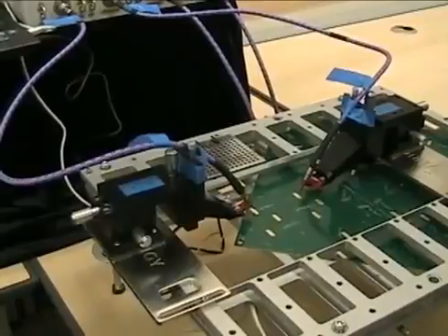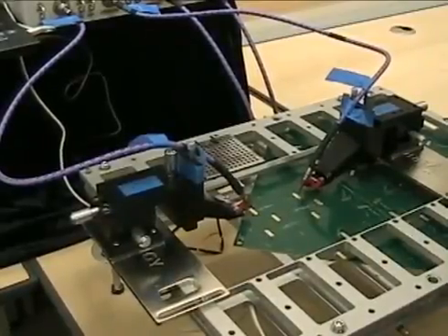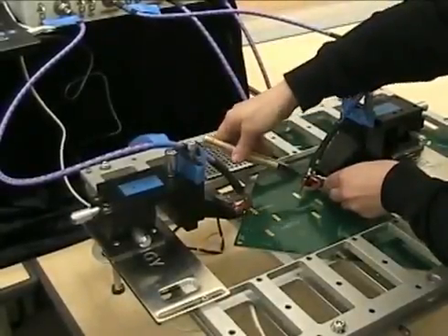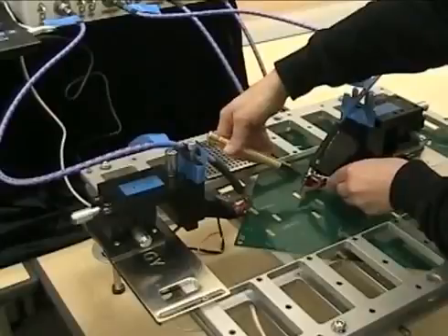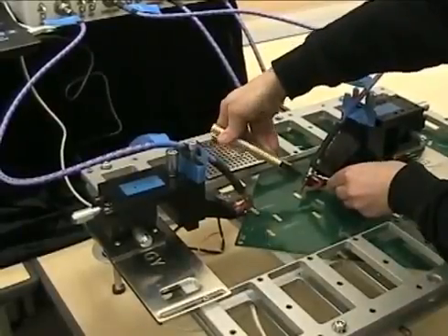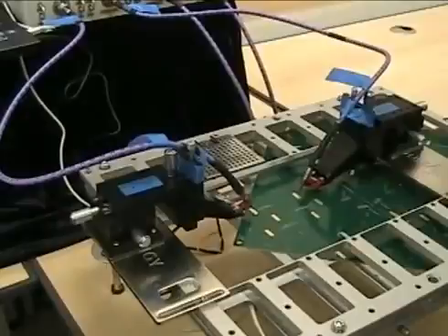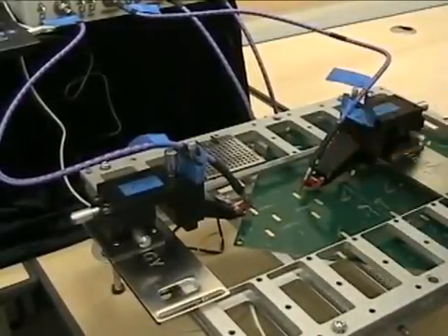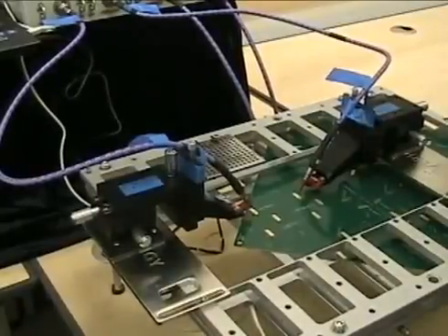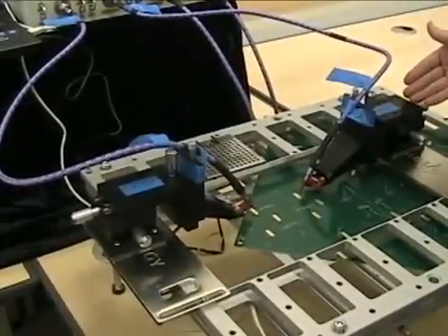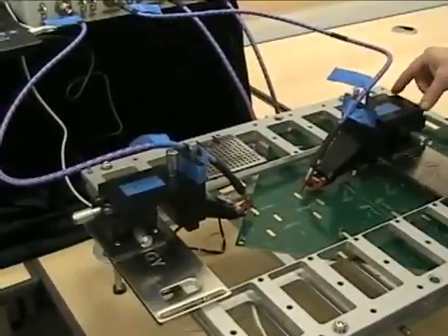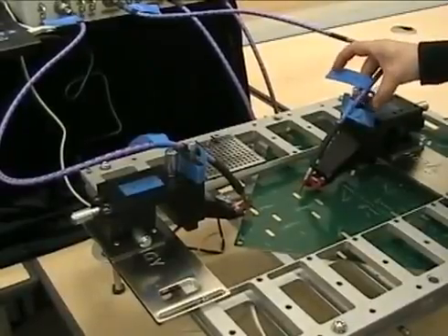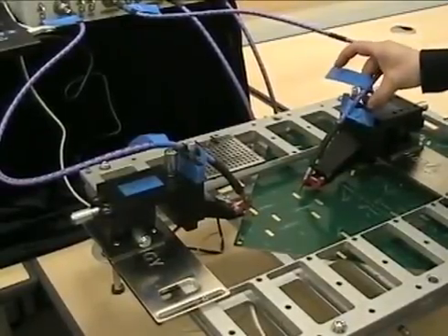Now that we have finished the calibration to the ends of the network analyzer coaxial cables, we can attach the microcoaxial probes. Again, we use the two-wrench system to hold the coaxial cable from twisting and apply the proper torque. The microcoaxial probes have a very small and delicate tip with 1 millimeter spacing on the ground signal ground tips. We therefore need a precision XYZ positioner for accurate placement of the probe tip, and it is always important to know which direction is up so that the probe tip can be lifted without damaging it.